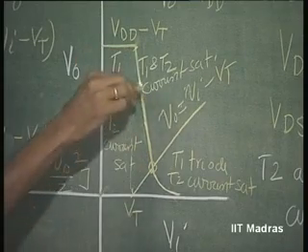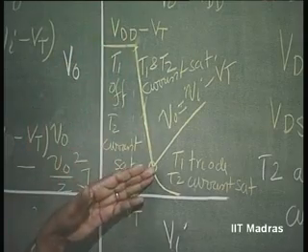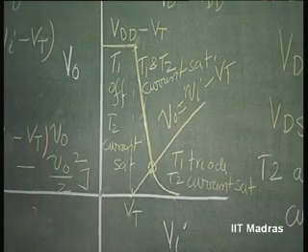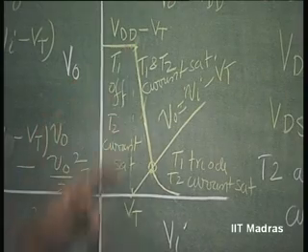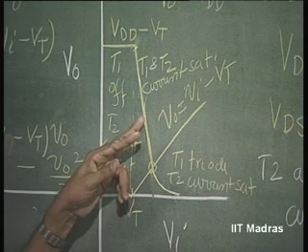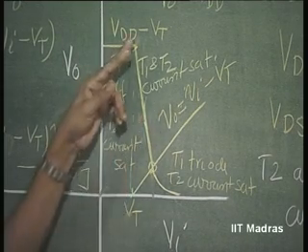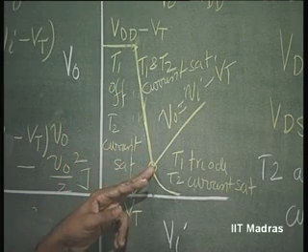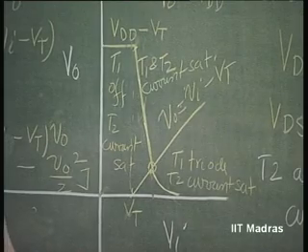In between these two can be the operating point, so that you get maximum signal swing. Okay. So, you can select appropriately. Once you know this point as well as this point, you can select appropriately the bias point here, okay, as the center point between these two, okay, half of this plus this voltage. That will give you the maximum swing.